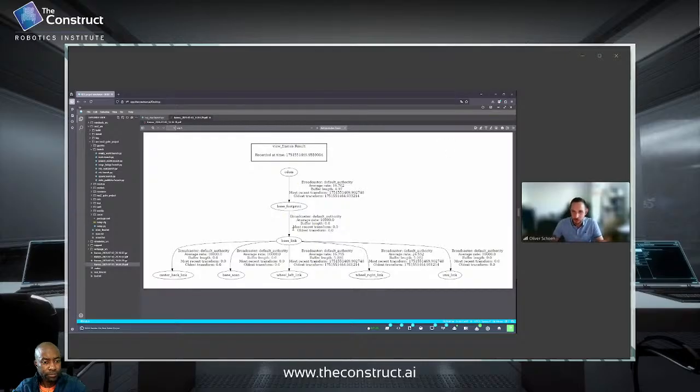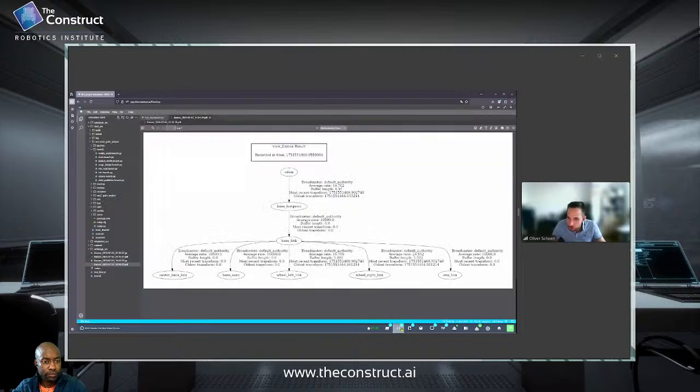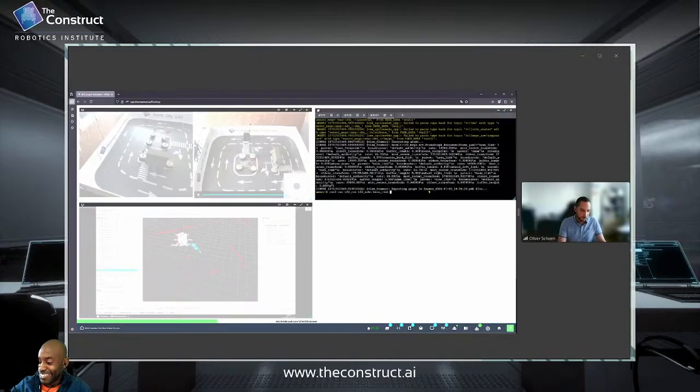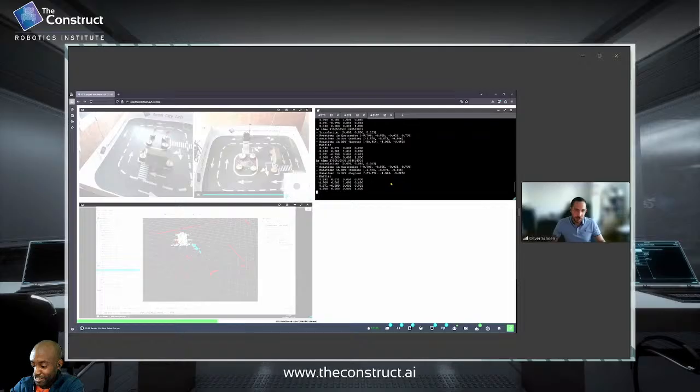And then when we just take, for example, the base link and now one of the wheels, like the wheel right link, we can just use the tool I mentioned before, the TF2 echo. We can say base link, and then it was, now I have to double check how it was called, wheel left link, for example. And then it will always give the transform information that is published. So it runs through with the times, of course. I will quickly stop, then we can have a look.